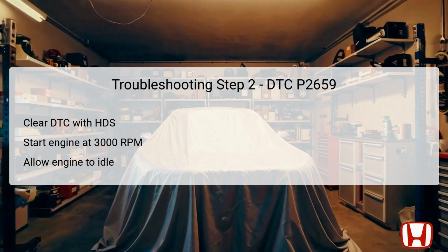After maintaining this speed until the radiator fan engages, which indicates sufficient cooling, the engine should then be allowed to idle. These actions are performed to observe whether the DTC reappears in a pending or confirmed state, which helps to ascertain whether the issue is persistent. This step is critical for determining the next appropriate diagnostics.